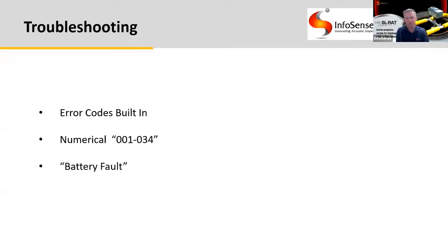Try recharging the unit first. If the error still appears, it could be something more severe, such as the amplifier circuit burned up or some other issues with the circuit board. The unit will need to come in for diagnostics to figure out what is causing this issue. It could also be a seized speaker that the amplifier is trying its best to move, but is overworked by the failed speaker.